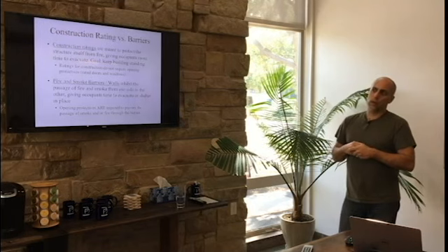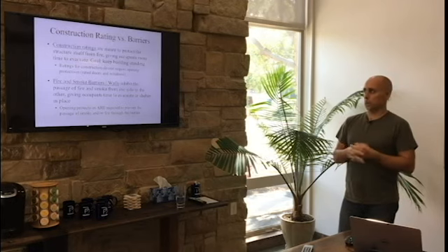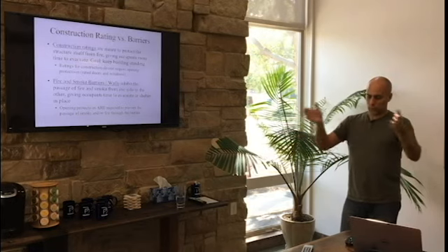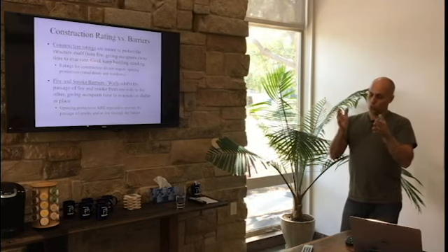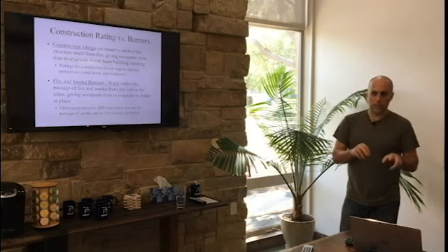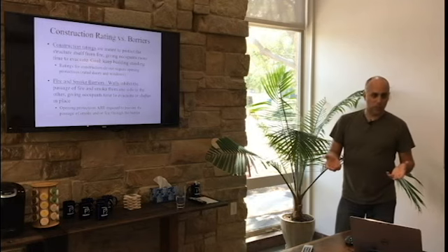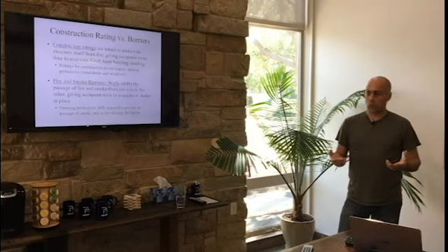So it's two different things. But you might have a bearing wall going down, say, both sides of a corridor. In a nursing home, we do this all the time, where your exterior walls are bearing and your corridor walls are bearing. But in a nursing home, which is an I2 occupancy under the IBC, your corridors are only required to resist the passage of smoke. They're called smoke partitions in the IBC. They don't even have a definition in the Life Safety Code. They just have to resist the passage of smoke.